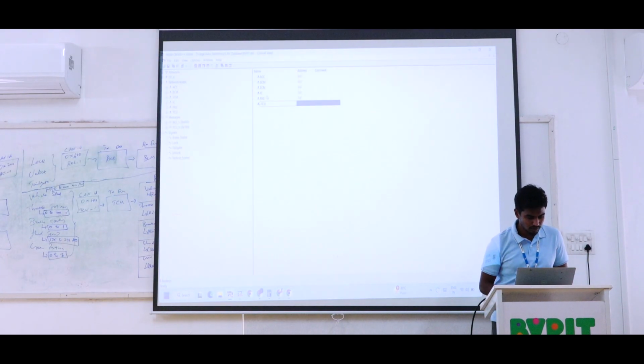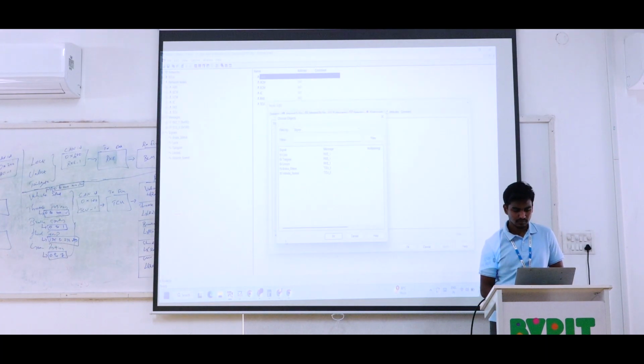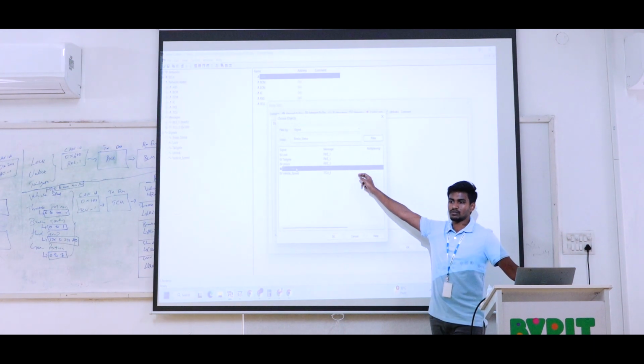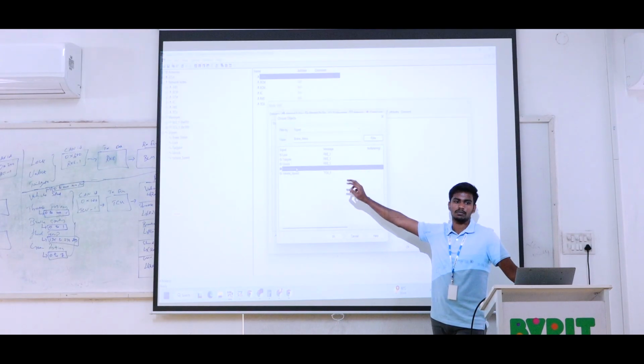So now, instead of ACC, I can mention ABS. For this ABS ECU we are going to receive individual signals. We can add only the brake status. It comes from the TCU message only, so the identifier will not change, and the transmitter will not change.